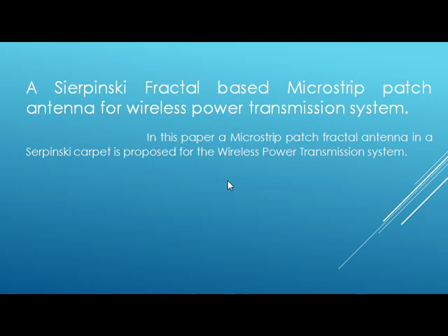So this paper cites the design and simulation results of the 2.4 GHz microstrip patch fractal antenna. The main advantage they achieved from using this Sierpinski fractal antenna is that the size of the antenna was reduced by 31.26%. It is a considerably high rate of size reduction for the antenna, and the simulation was done using Zeland Incorporated IE3D software. So that's what the paper cites.